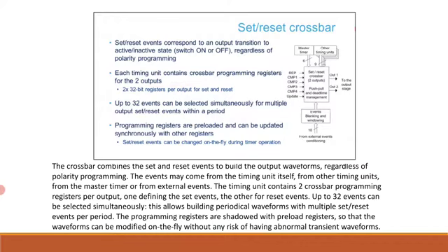So in parallel with compare units, each timer also embeds two capture units. The capture triggers the transfer from the current counter value into the capture register. This is useful for determining external timings and for the auto delayed mode discussed on the next slide. Typically, it offers the possibility to measure the effective duty cycle in cycle by cycle current controlled converters, where the PWM pulse is terminated when the current comparator trips.